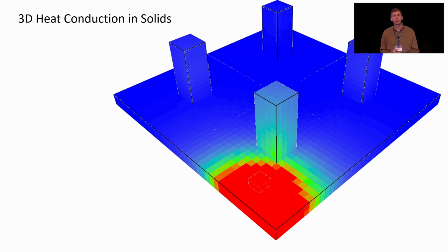However, you sometimes get into situations where you're looking at structural steel, or even compartments made with steel walls, and in such cases, it is important to consider the fact that the heat isn't just being conducted directly into the solid, but rather it's also being conducted laterally.